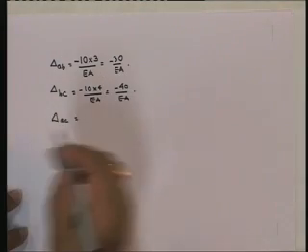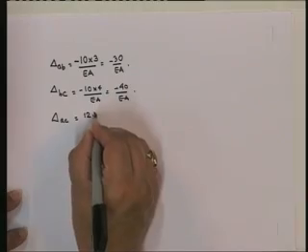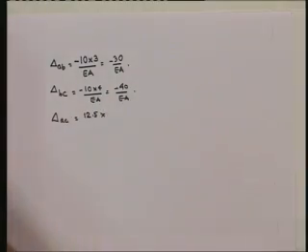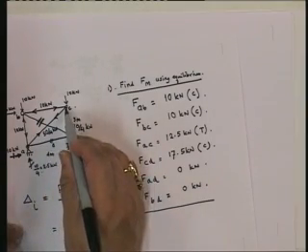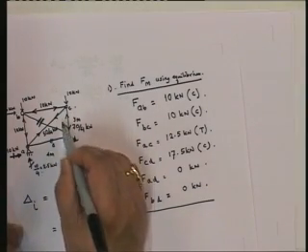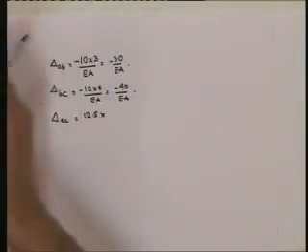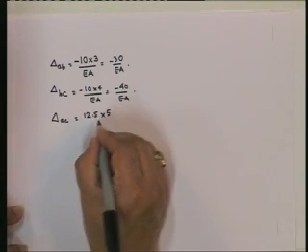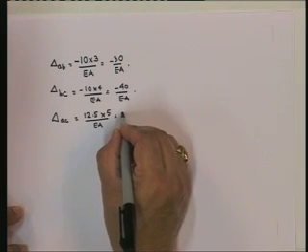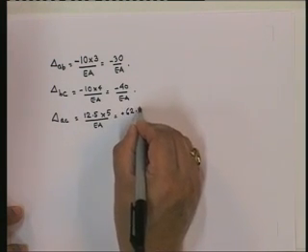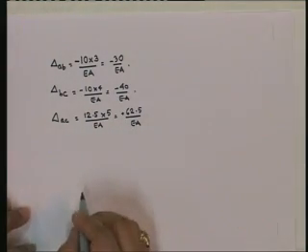Let's look at delta AC. Delta AC, the force is 12.5 tension. What is the length? AC. Since this is 4, this is 3, you can see that and this is 90 degrees, this is the hypotenuse 5. Okay, the total length of AC is 5, so it's going to be 12.5 into 5, and this is plus, so it's going to be plus 62.5 upon EA. That's delta AC.